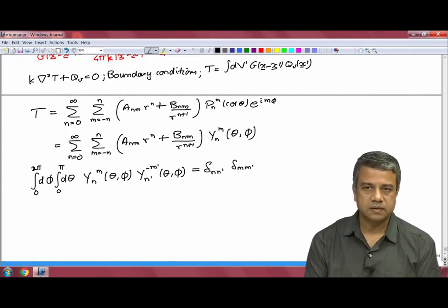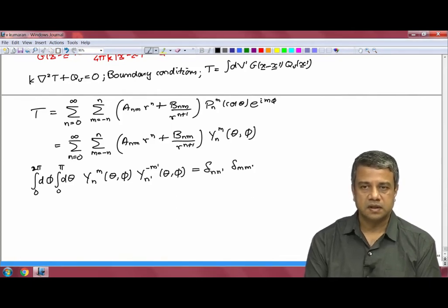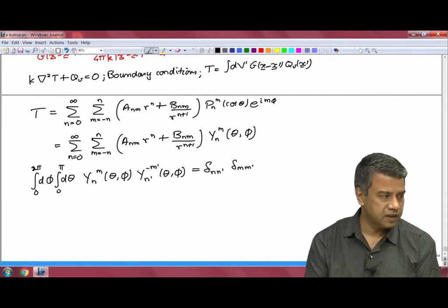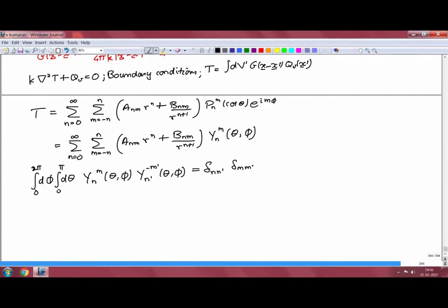And in the next class we will discuss forced convection in the limit of high Peclet number, where the ratio of convective and diffusive transport is large. That is the direct opposite of the limit we have considered here. Here we have considered low Peclet number, convection is small, we have neglected convection altogether and we have solved the diffusion equation. In the next lecture we will consider high Peclet number. Convection is dominant compared to diffusion. However, close to surfaces diffusion cannot be neglected because transport perpendicular to the surface is necessarily due to diffusion. That we will start in the next lecture.